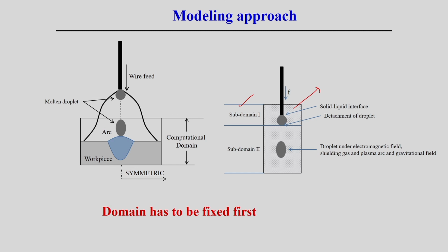Once it is in a liquid state, we can also start forming the flow field within the droplet. Apart from the temperature field, we can estimate the flow field. This flow field is influenced by the different driving forces for the detachment of the droplet. Once we estimate the flow field, we can find the condition at which detachment of the droplet occurs.